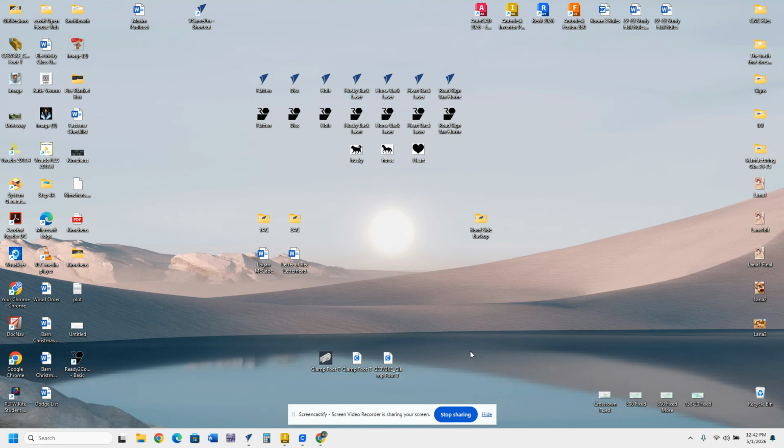So when you are done for each part, if you only have one part, you're going to have 3 files when you're done. Inventor file, IPT, Inventor file for Cura, which is the STL, and then the file that Cura will create for the 3D printer.